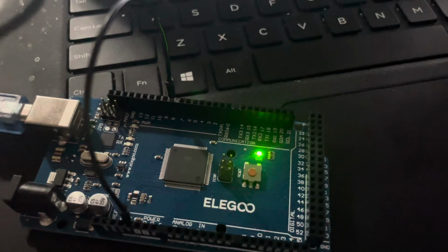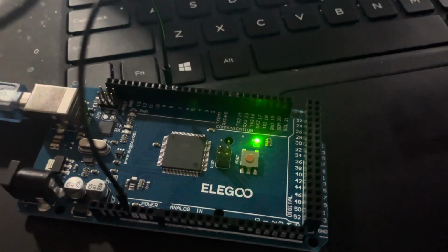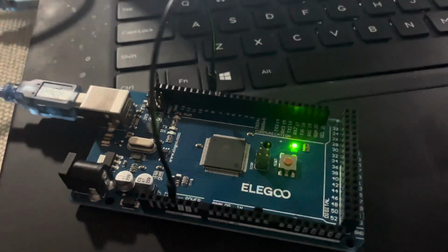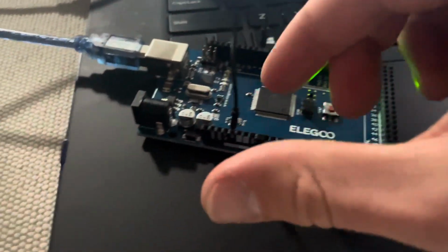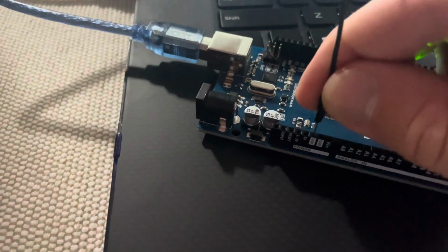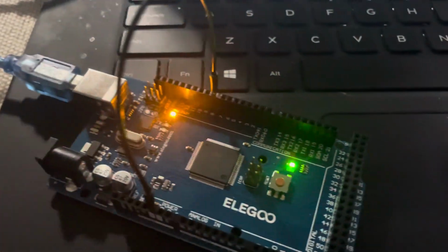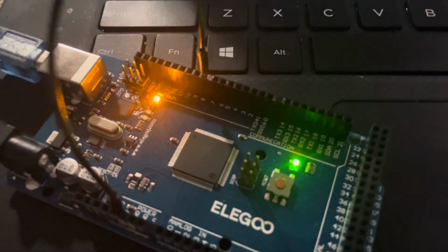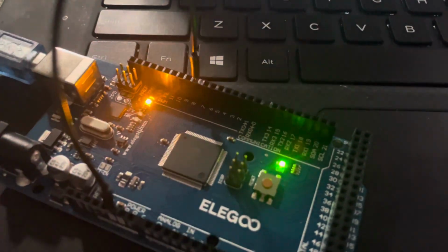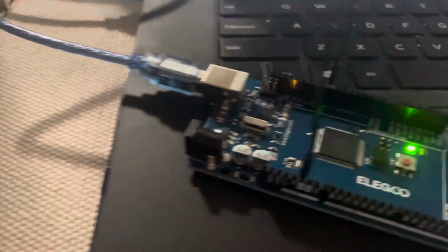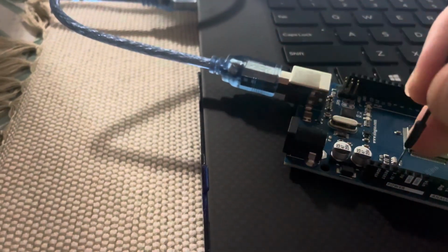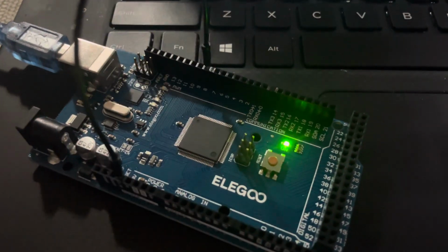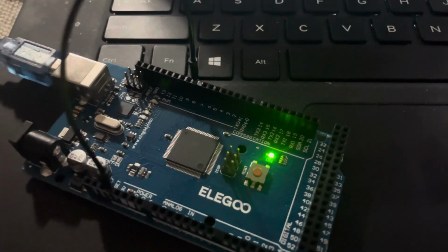And because that value is satisfied and greater than 0, because it's true, we are one second on, one second off with the delay. If we put it into ground, where no voltage is going through to pin 8, so the value is 0, we get quarter second on, quarter second off. And if we put it into pin 3, we go right back to 1 second on, 1 second off.